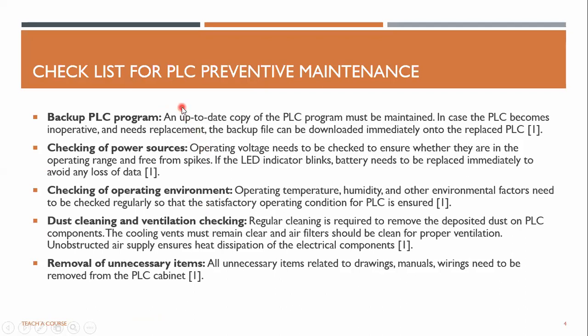Okay, right. When it comes to PLC, any technician or engineer has to deal with this checklist for the preventive maintenance of the PLC. It's a good practice. Make sure you remember these things, and you have to practice them when you go into industry, right? So the good practice is to back up the PLC program, right?